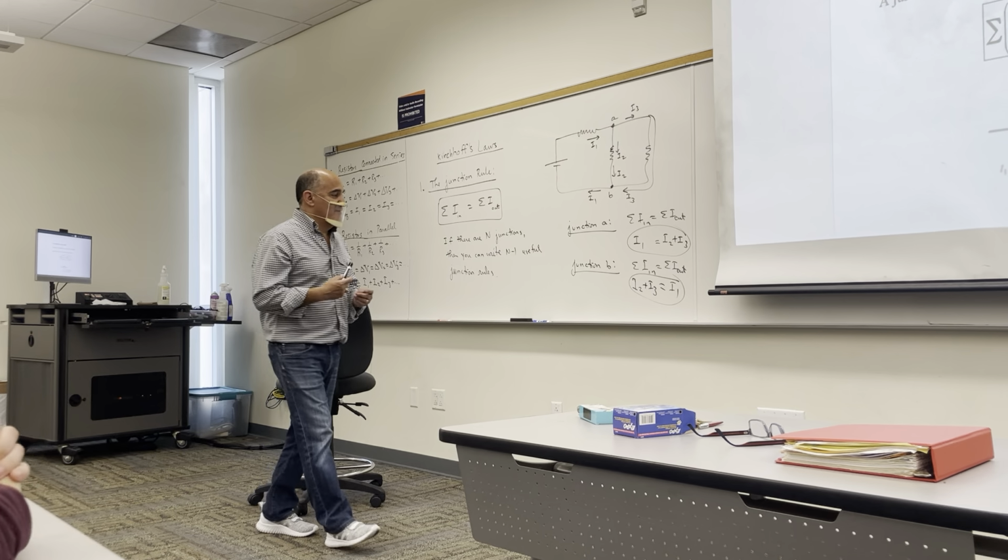So if you go through the battery from the negative to the positive, you went up in potential, because the positive means it's at a higher potential than the negative terminal. But if when you go through the battery, you go from the positive to the negative, you dropped in potential. So it's a minus, whatever the voltage is across the battery.